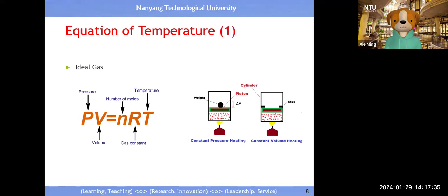So basically it means we can convert or relate temperature to resistance. Once you have a resistance, it's easier for you to convert resistance into voltage, right? And once you have a voltage, the good news for you is we have the analog to digital converter. Then you can easily convert voltage into a digital number, right? Okay, so that's for you to know.